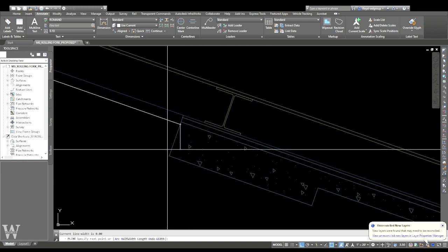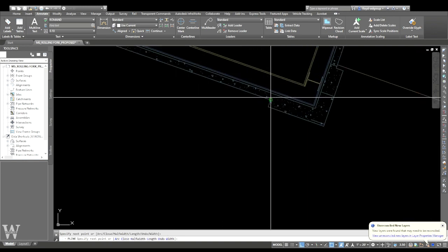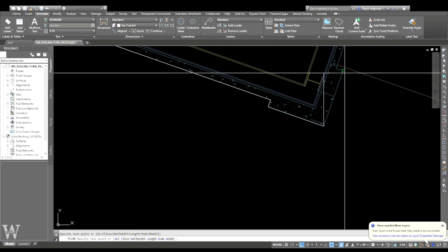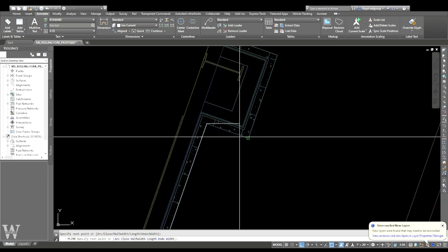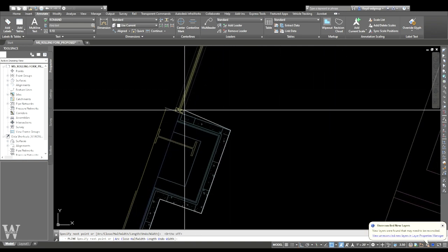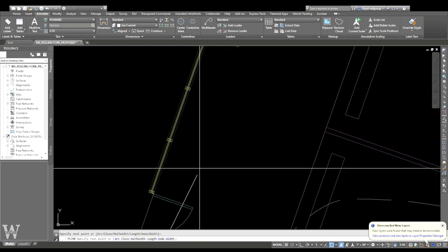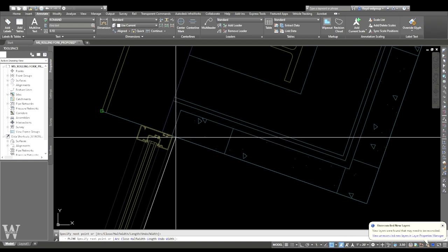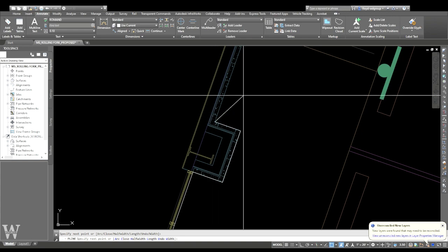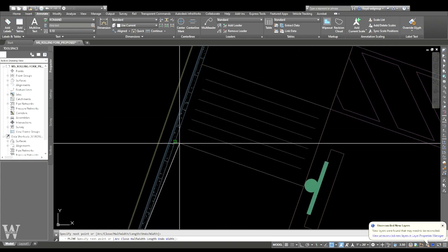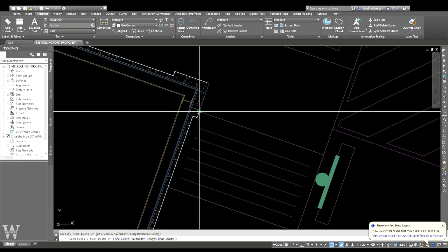So I'm going to continue that polyline. And I was working with this the other day, and I had a guy that was watching me and learning, and he asked me why my lines were trying to go straight. Well, that's because I didn't turn my ortho off. And ortho is orthogonal, which means straight up and down, left and right, 90 degrees. And I tend to sometimes leave it on and sometimes I don't. So I just used F8 to turn it off.